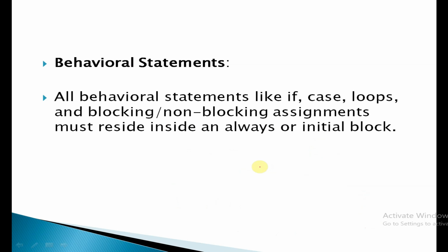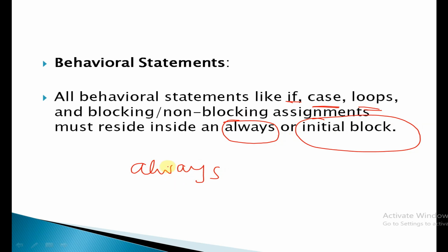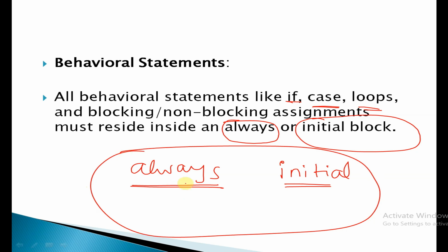Now, behavioral statements. In behavioral modeling, we have behavioral statements like if, case, loops, and blocking and non-blocking assignments. All of this should be present inside an always block or inside an initial block. Outside these blocks is not a valid syntax. Is it clear for everyone?